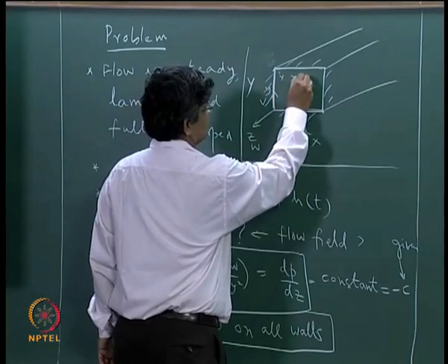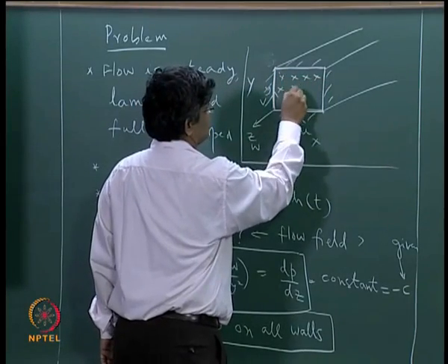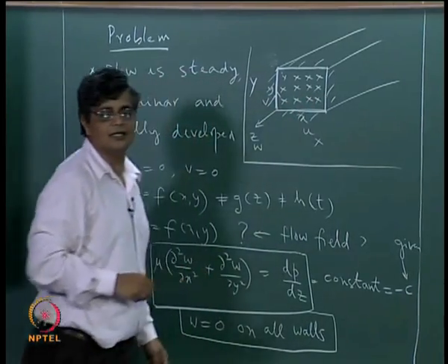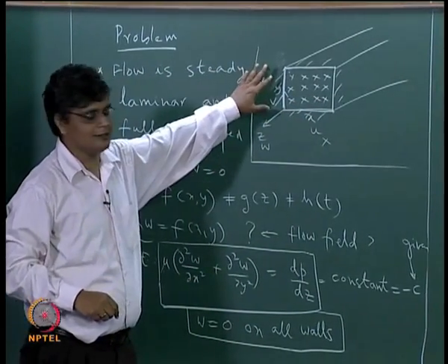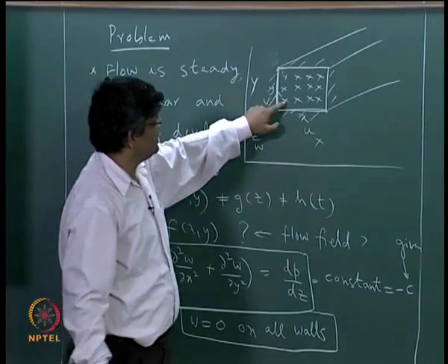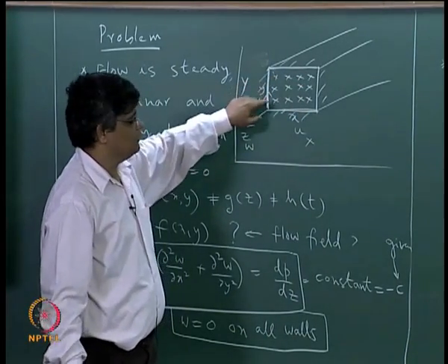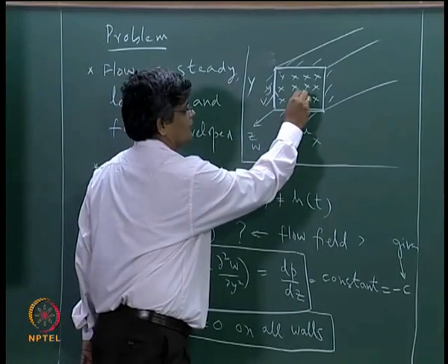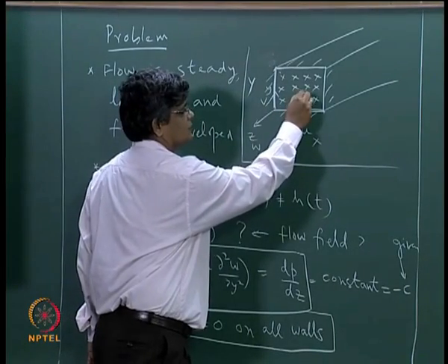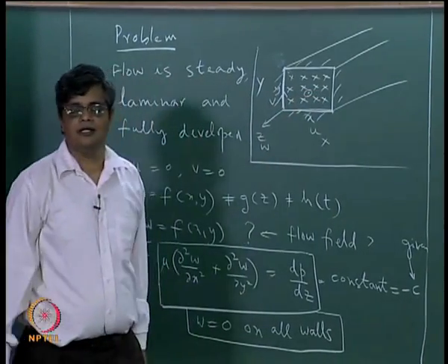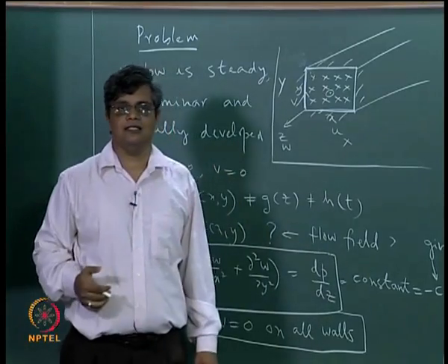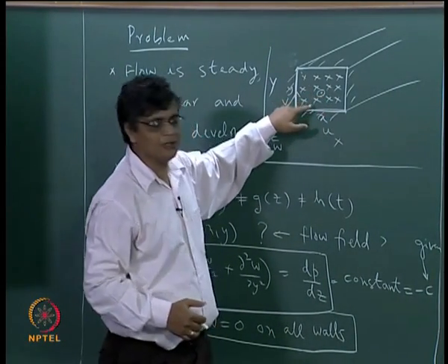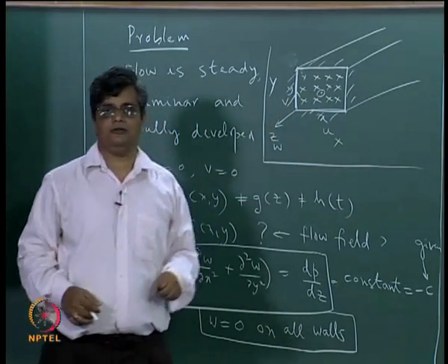Typically we give it at several points which are in a fairly ordered logical sequence like this. So at these points marked by the crosses, we give the solution. And if you are looking for a solution at this point, we don't get it from CFD directly, but given that the solution is known at these neighboring points, we can get it by interpolation.